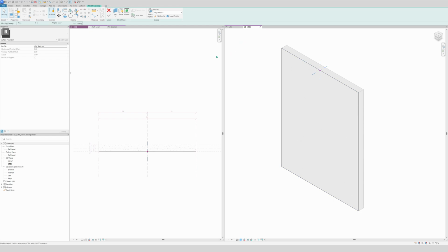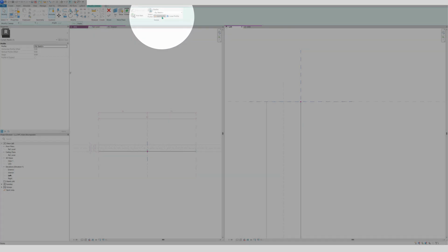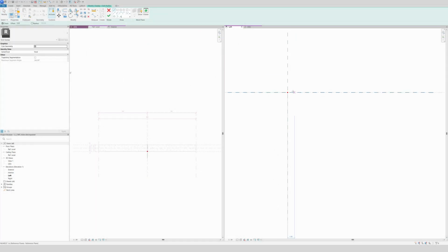So right here we go to the left of it. Why? So we can easily draw the profile. So we're gonna click on edit profile, and now we're gonna draw the chamfer. So we will use maybe 1.5, and then we're gonna use 1.5 also, and just do it by this, and we will see if we move it with arrow keys, they are connected to each other. And that's really important, because we will make a parameter so we can edit the chamfer.